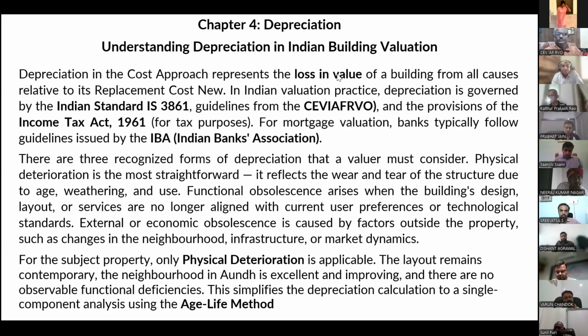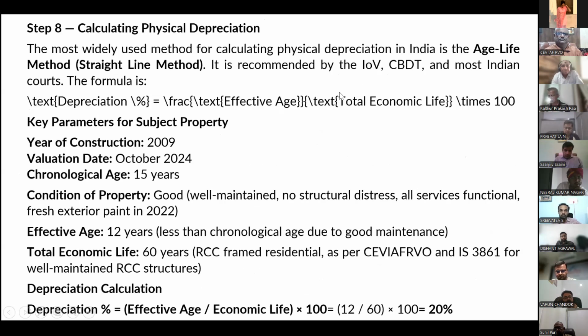So here you have gone to the site, year of construction is 2009, valuation date is October 2025, age is 15 years, condition of the property is good, it is well maintained, no structural distress, all surface is functional, fresh exterior paint in 2022, you check it.